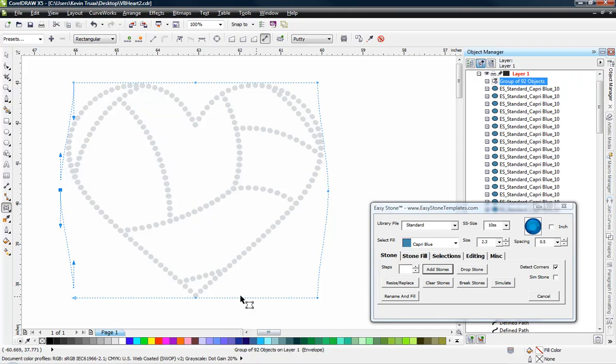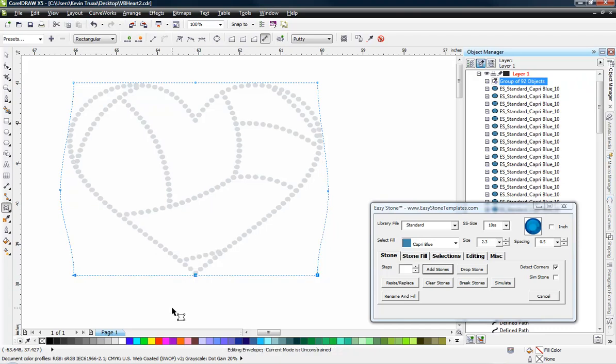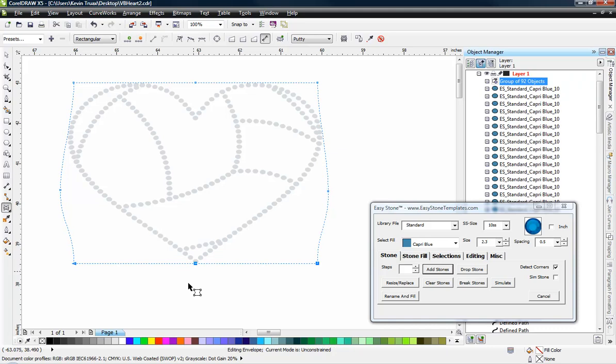And then we're going to take these three control points along the bottom by clicking and dragging all three of those control points. You can see all three of those are now highlighted, and I'm going to pinch. Let's pinch, go straight up. We can hold our shift key down if we want to constrain it to be perfectly up. Now remember, I said do baby steps, because you don't really know how big a change we're going to make here. But you can see there, that looks pretty good. And we could move it up a little bit more, maybe.